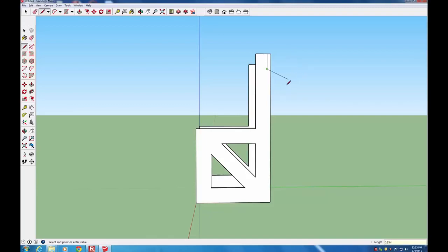And if you're in the line tool and you want to start drawing lines again, but you don't want to start from this endpoint, you can just click Escape on the keyboard, and you'll stay in the tool, but it will sort of forget about that last point you were on. The next spot we're going to go from is down here. We're going to go up 0.025 and over 0.025. Then Escape, and then same on the bottom corner. And so now we have these three guide points that we're going to use to place the rectangular cross pieces.